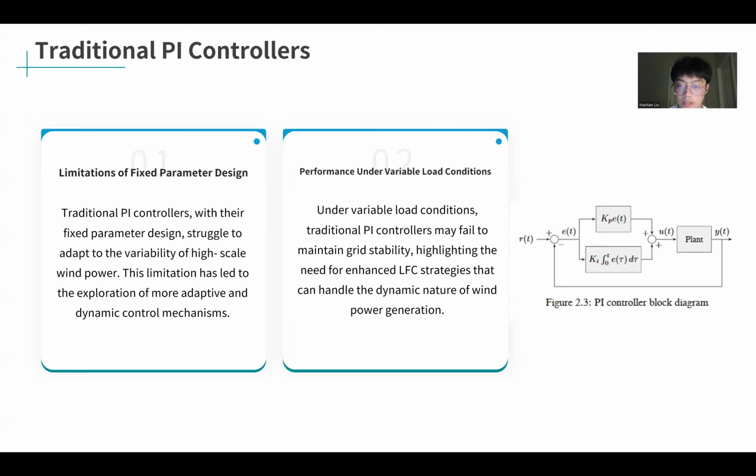Also, the performance under variable load conditions is limited. Under variable load conditions, traditional PI controllers may fail to maintain grid stability, highlighting the need for enhancing LFC strategies that can handle the dynamic nature of wind power generation. Both of these drawbacks are caused by the instability and unpredictability of wind power.